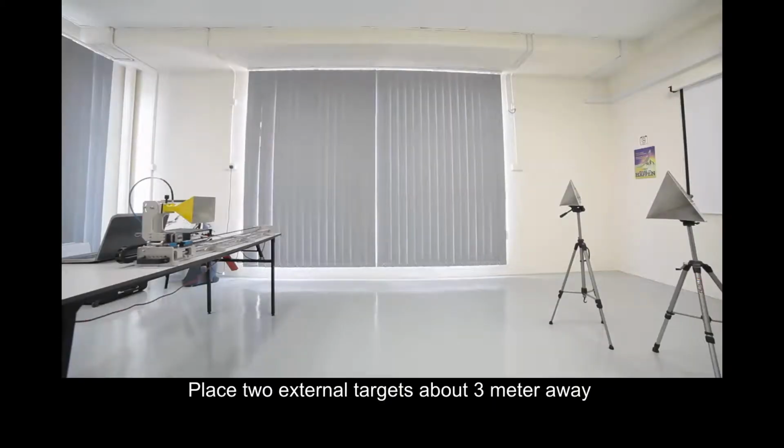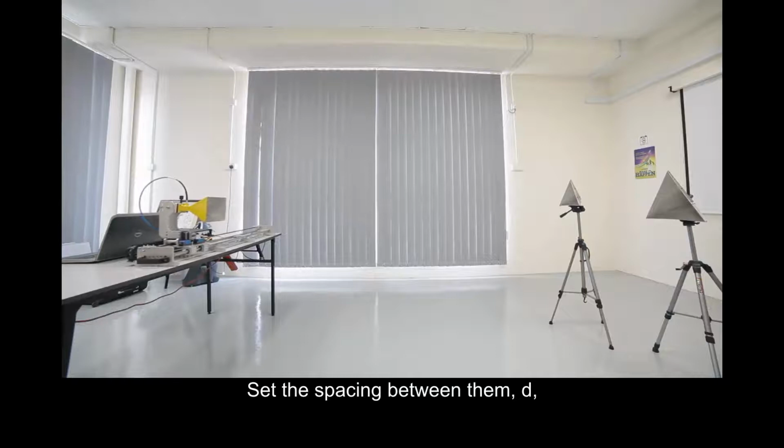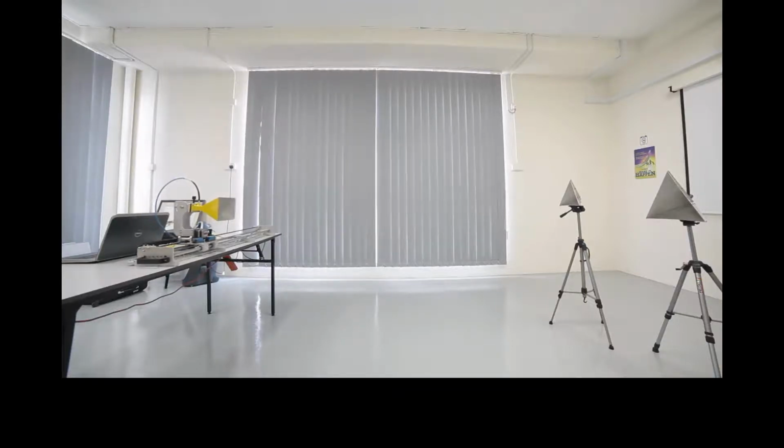Place two external targets about 3 meters away, at the middle of the scene to be scanned. Set the spacing between them, d, about 0.4 meter along the azimuth direction.